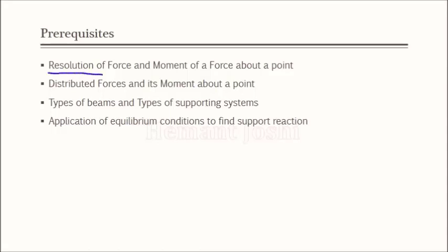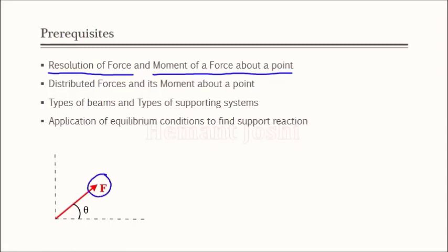First is resolution of force and moment of force about a point. If I wish to resolve a force in orthogonal components, and we have been supplied with the force in magnitude and direction, then for the direction theta, the adjacent component is always the cos component and the other component is always the sin component. That means whichever component is adjacent to angle theta is always cos, and the remaining component is sin.